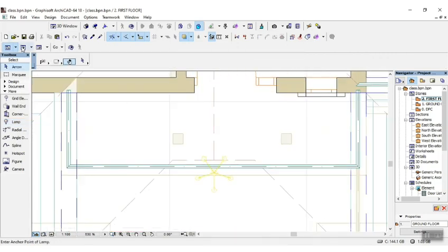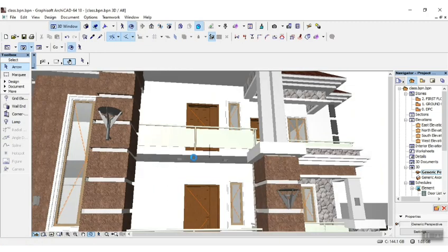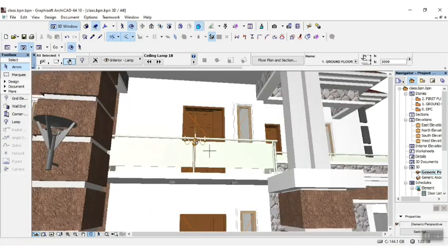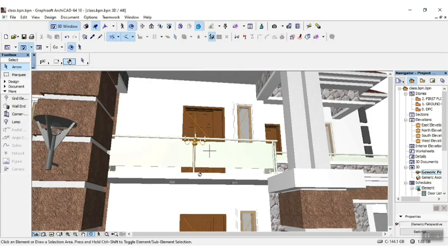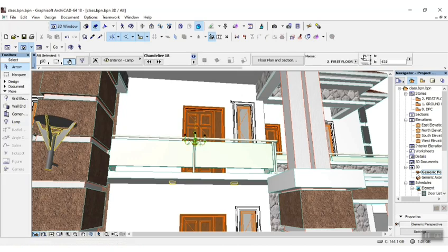Okay, so you go to your 3D to determine the height of what you just did. You select what you just brought to the spot. You select it like this. Then you determine the height to be 3.1 meter. So it's offset upward. 3.1 meter. Let's see.